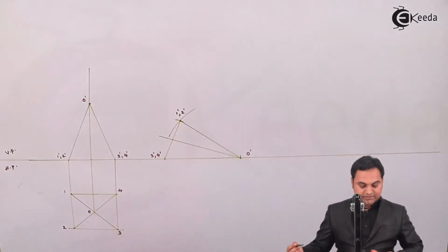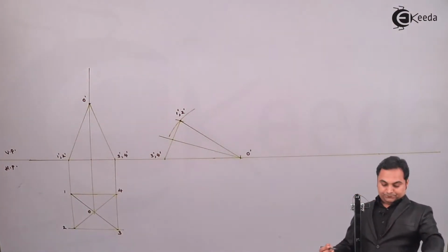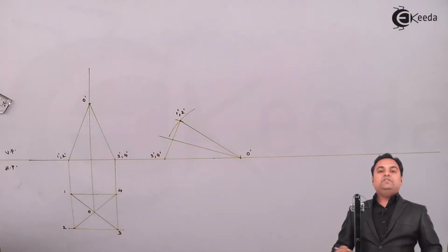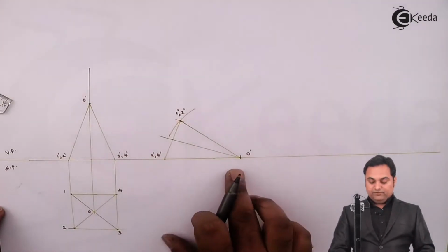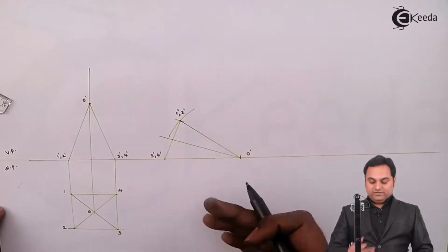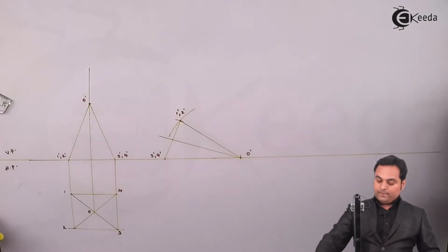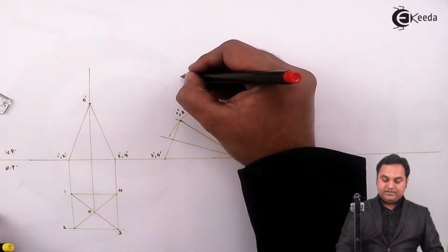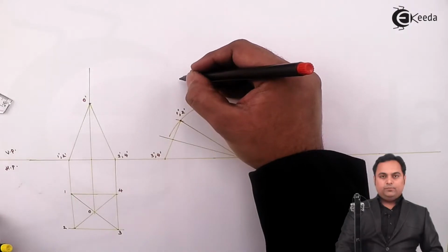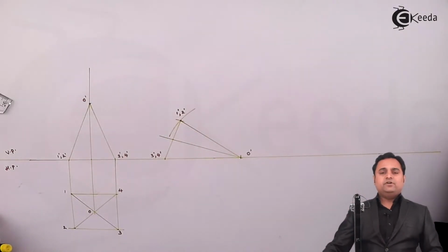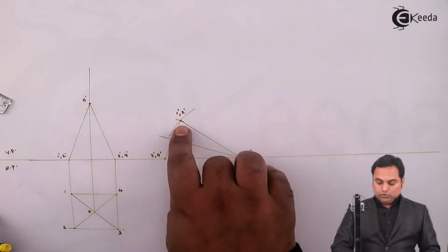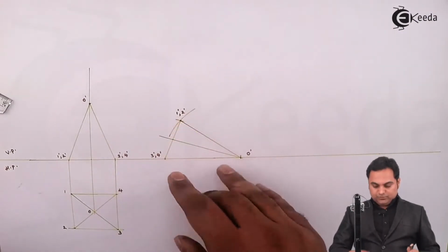Light line which indicates the axis. Now when this pyramid is tilted, here we have got the front view of that. Next I will be plotting the top view. For that, observer is there at the top. When we are looking at top, those points need to be projected first which are visible. So this complete base is visible to the observer.